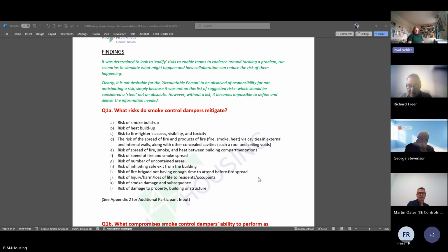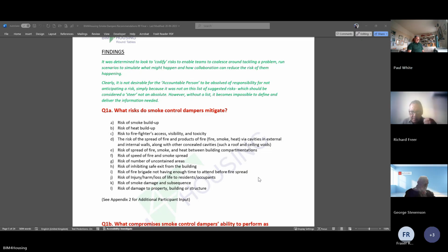So FD, MFD, SCD. You don't need motorized in front of SCD because they have to have a motor. It takes out all the confusion if you just stick to those three definitions. Well, we've said smoke control dampers, so let's get on. I can back Paul 100% there from Belimo's point of view.